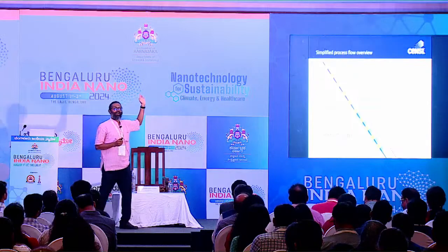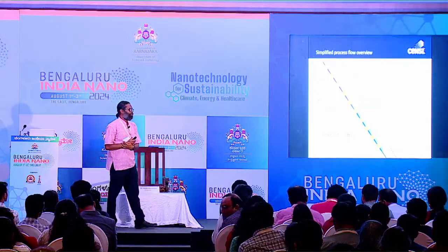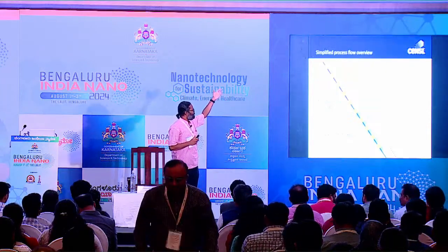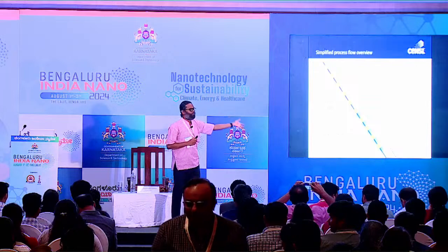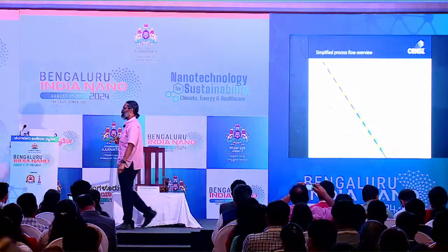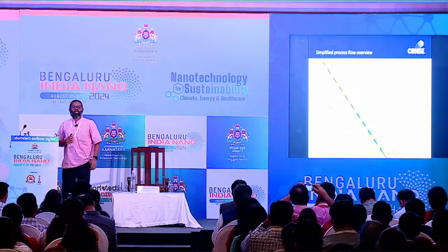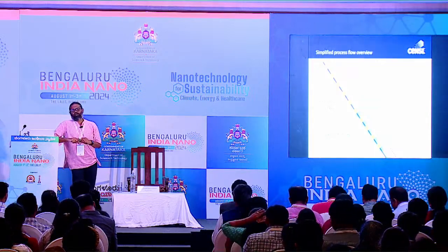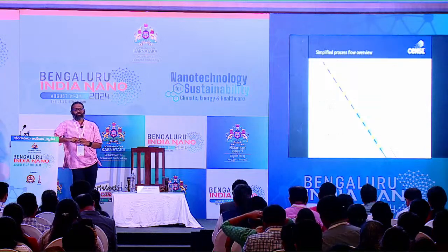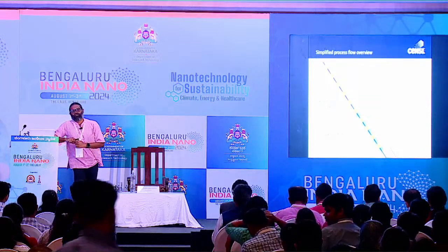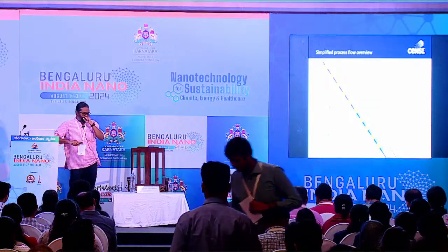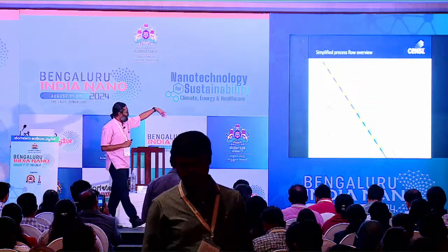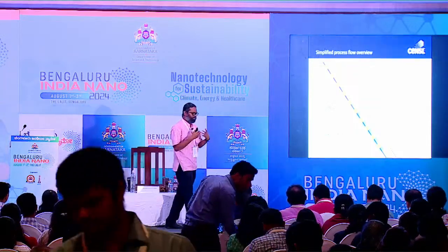And the process flow will have multiple steps, right? Starting from isolation, implantation, gate, silicide, contacts, metals, and so on. So there are a number of processes that you need to do. A typical advanced level processor or a memory would take anywhere between 400, 500 steps. Okay, so that's why they are reasonably expensive. And then we classify these steps based on the functionality.